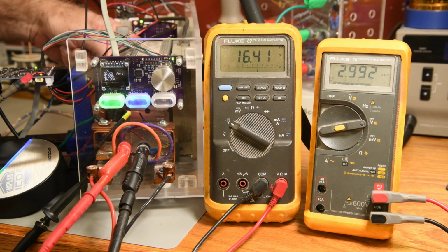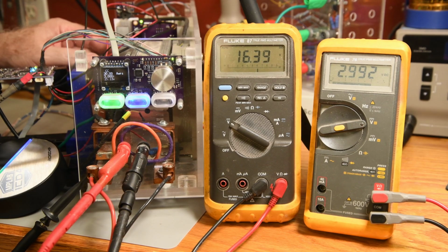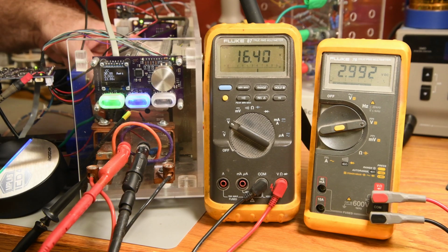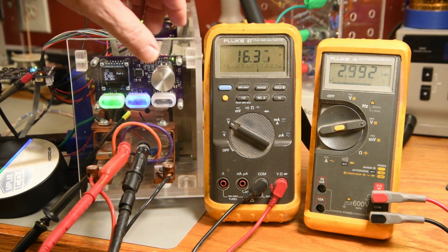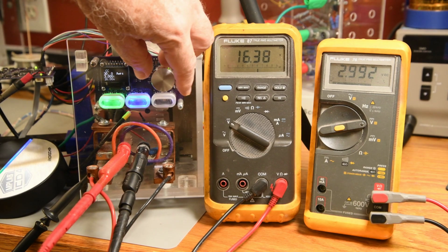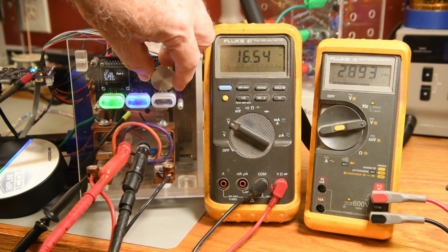I think the first problem to tackle is the oscillations at lower currents, by far the biggest problem at the moment. It may be I need to implement something like PID control in the output code. I'll do a bit of thinking on that. Once I get that under control, I think I need to go ahead and redo the power supply. Really isolate the power to the fans from everything else, and maybe look into some ferrite beads. I would like to eliminate those very short noise spikes. The less noise, the better. So that's 2 big tasks ahead.